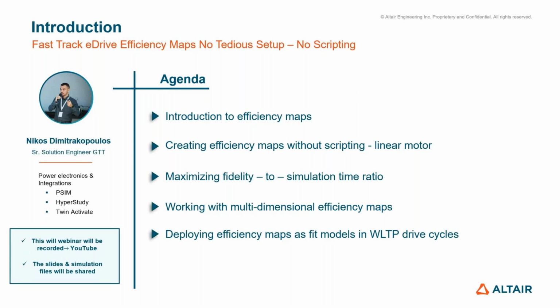By the way, let me also say that PSIM can co-simulate with Simulink in case you want to have your control stage inside Simulink and work with PSIM when it comes to the power stage. The heavy loading of the simulation for the switching part will be handled by PSIM, and Simulink will only have to handle the control and the sampling rate. Okay, I'm going to end and share the results.